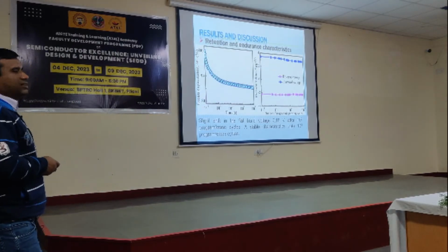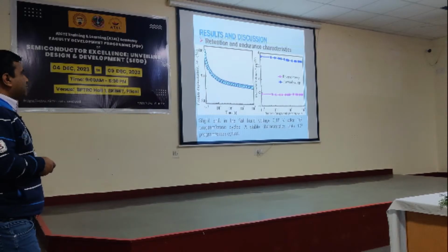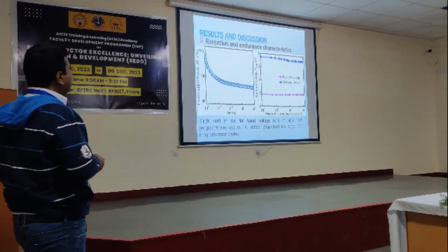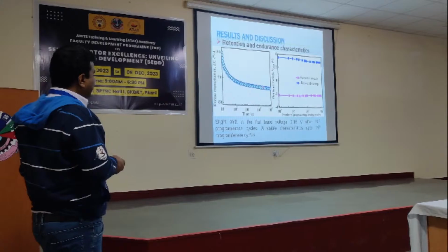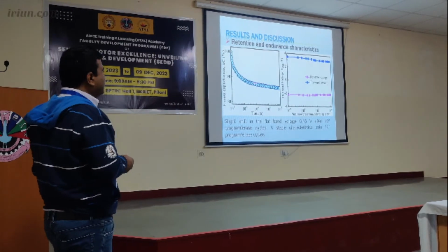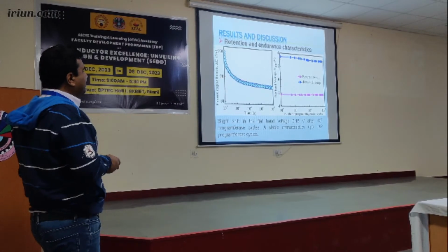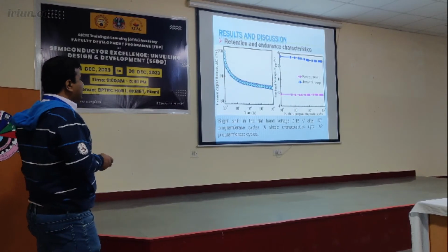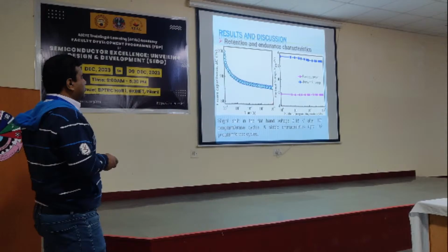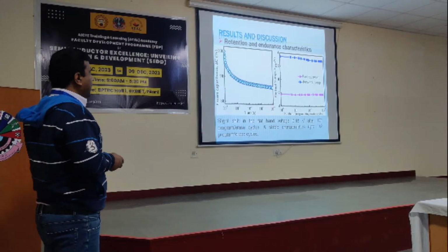Now this is the charge retention as well as the endurance characteristics of the devices. You see, almost 90% charge retention is happening in the case of these devices, which is quite good, even after 10 to the power 5 seconds. Okay, almost 1 day.